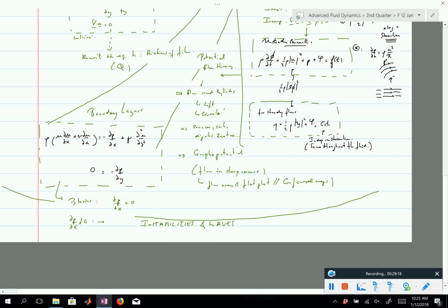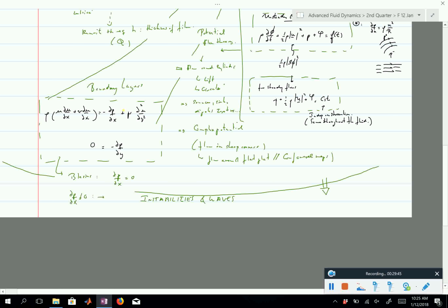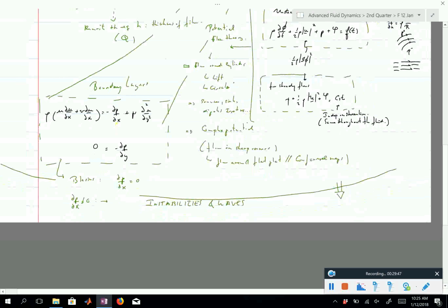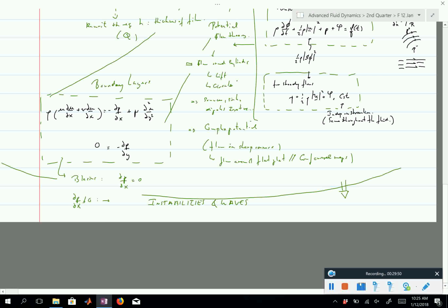Right, you have instabilities all across Reynolds number in many different cases, but the ones we discussed were really towards the higher end of Reynolds number, so it was mostly here. We didn't discuss any instabilities which happen when the flow is dominated by viscosity, but you have some, the Saffman-Taylor instability, or the Rayleigh-Plateau instability, and there are many. But we discussed here gravity waves,